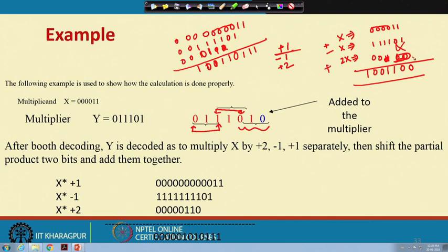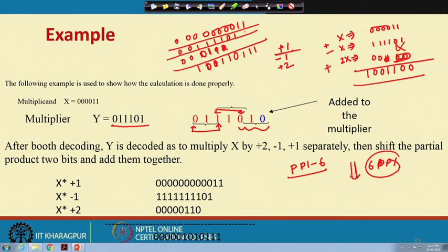So, now if you see my point, how many partial products am I generating, given that I have considered this y of 6 bit? Using the array multiplier, if I want to do this, how many partial products will I get? I will get a total of 6 sets. So, for the added depth delay, 6 partial product sets have to be added, so the depth will be 6.